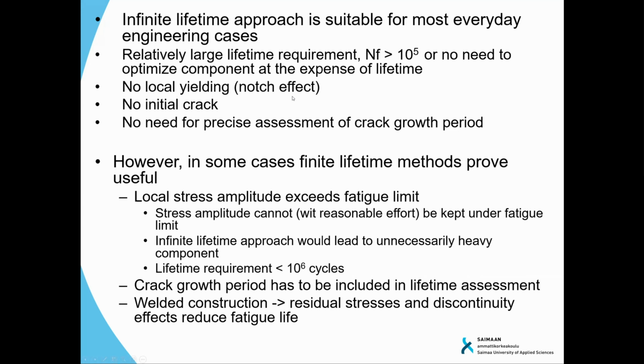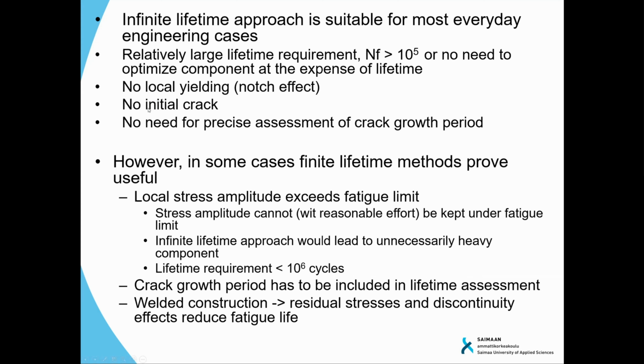Also, it's important to note that there shall be no local yielding due to the notch in the component. If there is local yielding due to the notch, we cannot apply the infinite lifetime method because we are not in the range of this method. Also, for the same reason, we cannot apply it if there is already an initial crack.